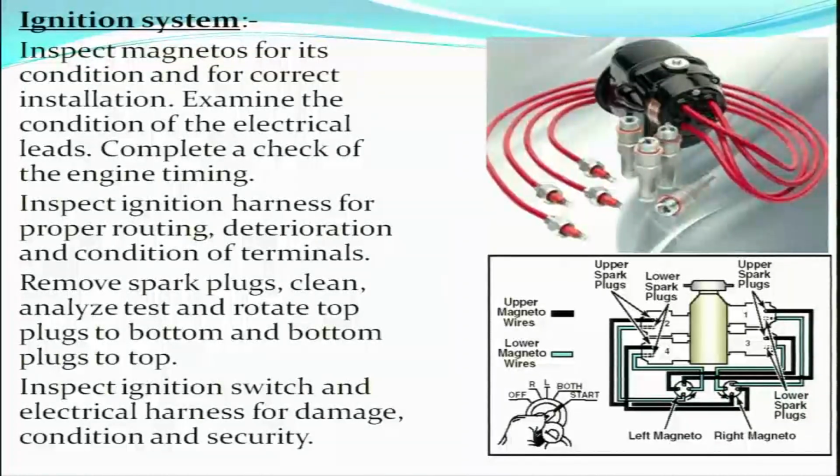Inspect ignition harness for proper routing, deterioration and condition of terminals. The ignition harness, you can see this harness, is checked for proper routing, deterioration and the condition of the terminals. These terminals are inspected for condition.